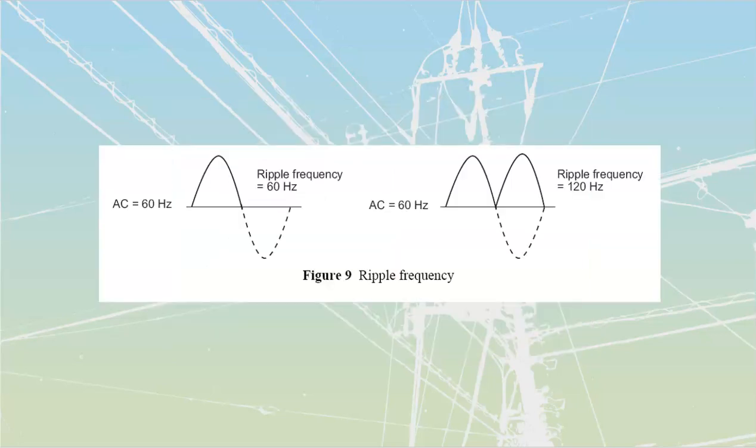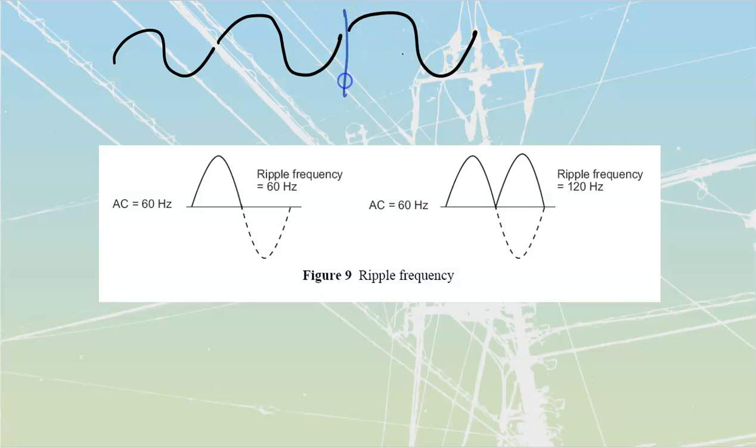Let's talk about the waveform that we are going to get out as well. Our waveform is going to have a ripple. We've talked about that there's a ripple voltage and there's also going to be a ripple frequency. Frequency is from where a waveform starts to where a waveform starts again, right? So for a regular 60 hertz waveform, we are going to take 16.66 milliseconds, and then that is going to be inverted. So that's my measurement that I have. That's where we get frequency from. You should remember this from first year, I'm hoping.